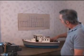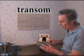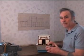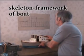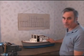The piece of wood on the very back of the boat is called a transom. That supports the outboard motor, and it's what the bottom and the sides fasten to. The keel is also fastened to it, and that completes the backbone of the boat, what we call the skeleton of the boat. Now, the frames that go crossways in the boat, there are different kinds of frames.